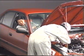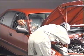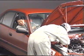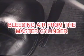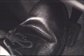2 people should conduct the operation. Use mutually understandable signals and confirm each step of the operation with each other as it progresses. First, bleed air from the master cylinder. Confirm that there is adequate fluid in the reservoir tank.